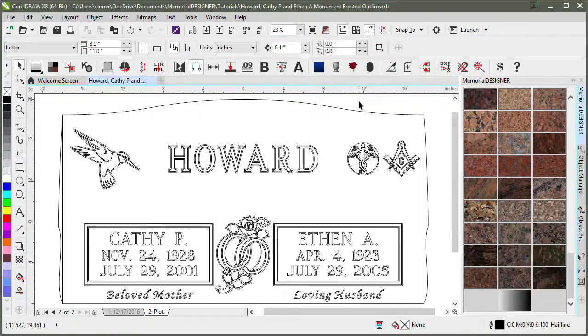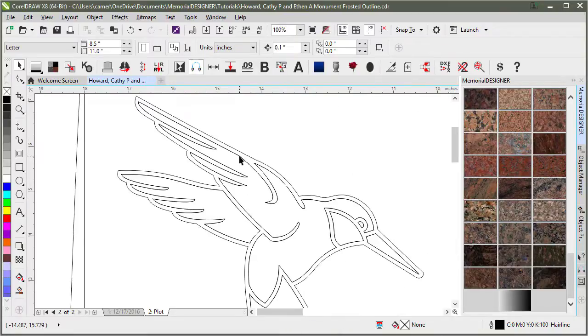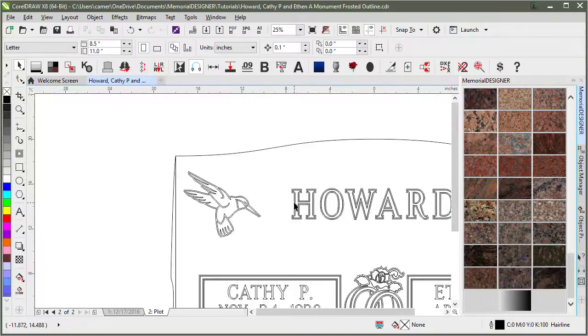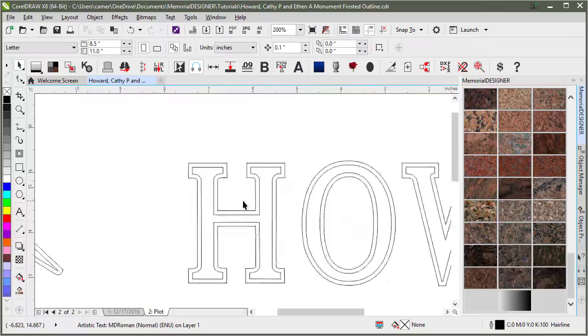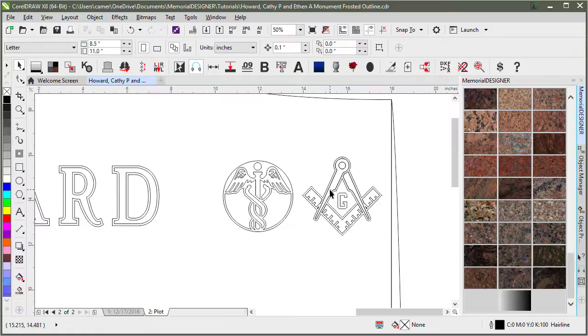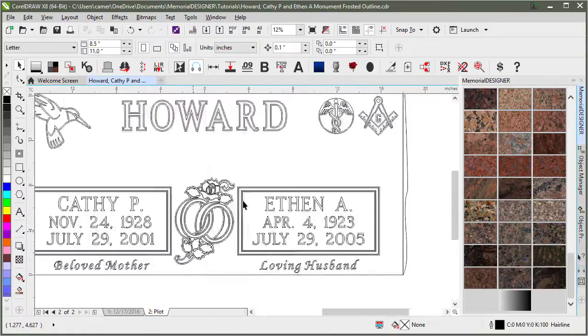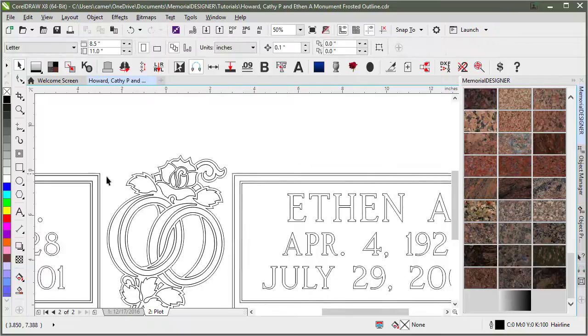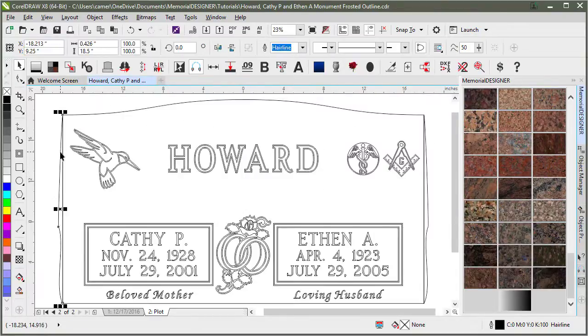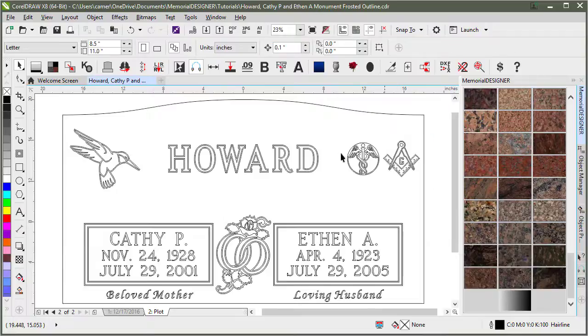The plot page is actually set to clear all of those bevels for you, but there's still the duplicate lines, and so you'd have to go in and manually take all those pieces that were duplicated and delete them. Or the other option is to go ahead and send out your cut file first, create your plot page first before applying any of the bevels, which is a way of doing it as well. That way you don't have to go in and remove all those duplicate pieces.